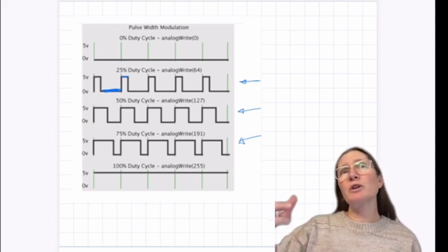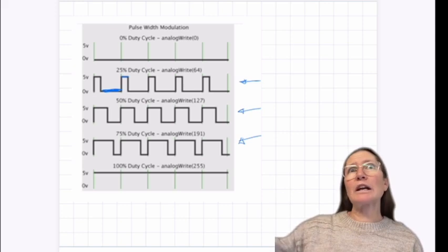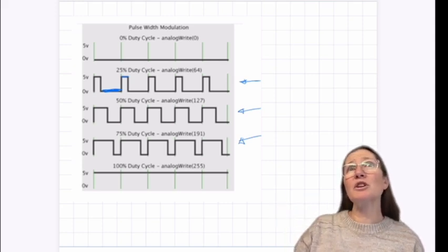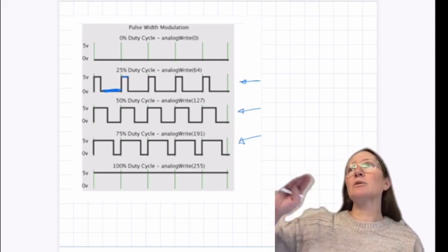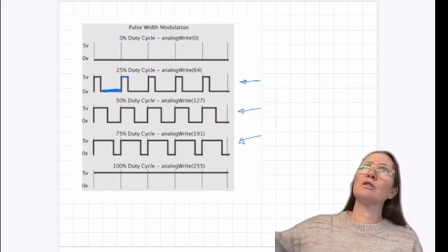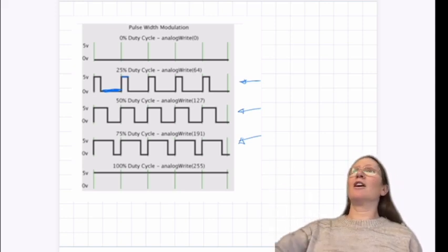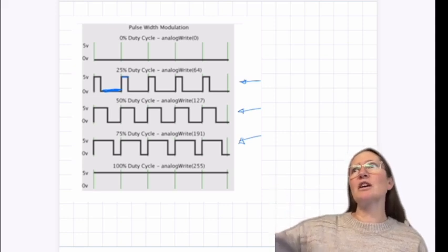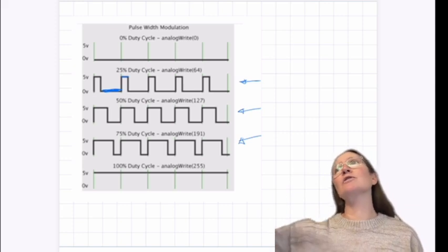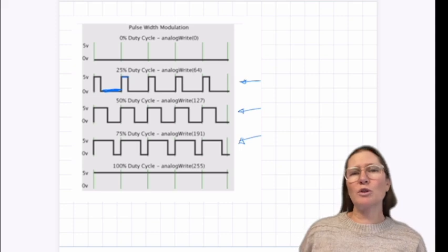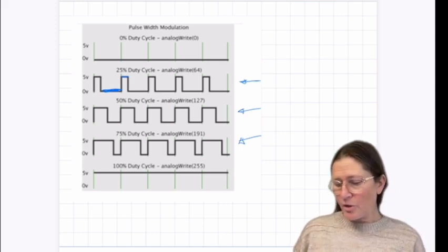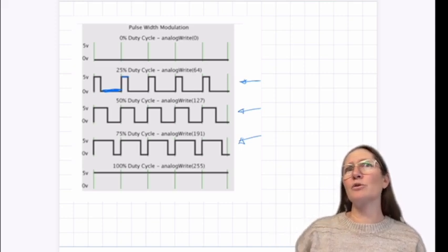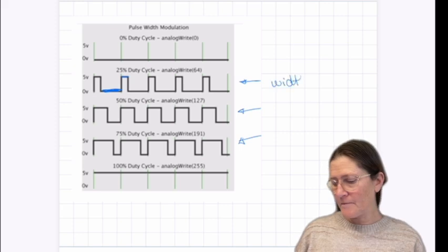So to control the speed of this, you can rev it up, go off for a second, let it slow down a little bit, rev it up again a little bit, and then slow down. So that will actually control the speed portion of it, so you can time it correctly to keep that more constant. It's a very slow transition between them, so it's not like on, off, but you'll be able to rev it up to a point where you can almost keep it steady by letting it coast a little, slow down a little, coast, slow down, coast. So it will control the speed of it. The width of how long it's on helps to control the speed of the motor, so it's related directly to speed.